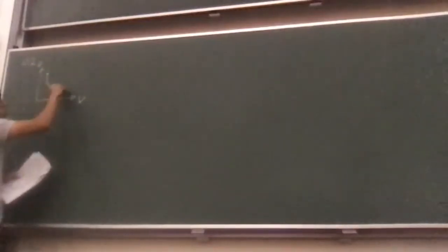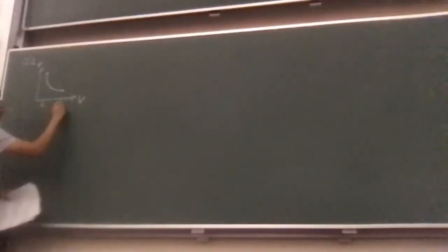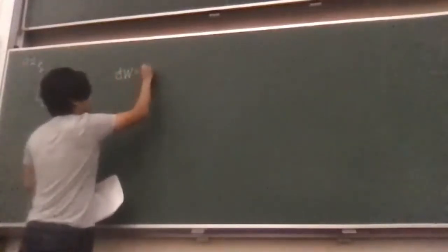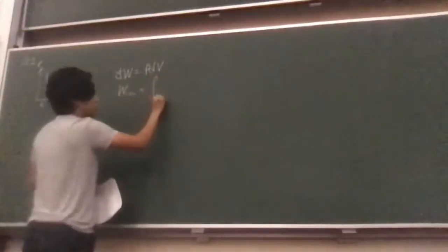So question 2, very similar. You've got an ideal gas expanding from V1 to V2 adiabatically. Looks about the same, except it's now an adiabat instead of an isotherm. Derive an expression for the work performed by this gas against an external load. What data would you require to evaluate and determine a constant result? So same thing, figure out the work by doing PdV. So W from 1 to 2 is equal to the integral from V1 to V2 of PdV.